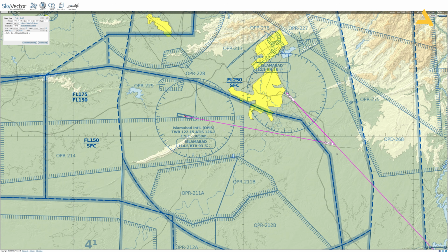As your plane is moving in this direction, your radial is changing. So right now, if you draw a straight line from here, you can see the radials are changing. So once you are here, you would be on 278. But over here, if you draw a straight line, you're on some other radial. You just have to actually point in this direction from the VOR. You just make this line. I'm just drawing it with the help of the mouse. But obviously, you are somewhere here near.